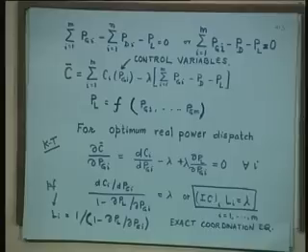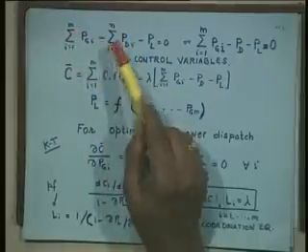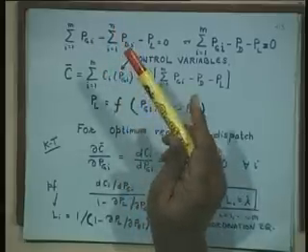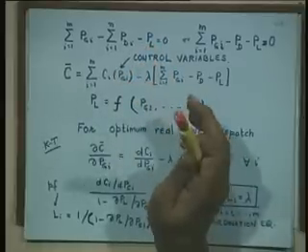This is the equality constraint. Summation of total power generation at m plants minus all load at all the places. N is the number of load buses, number of nodes, number of points where load is there. It is not necessary to have load at all the buses. Never be under the impression that a generator can be at all the buses, because it is a costly affair. It is normally 10 to 15% of total buses that have generation attached to them. This we have done in our load flow chapter. Minus PL, PL is the losses.